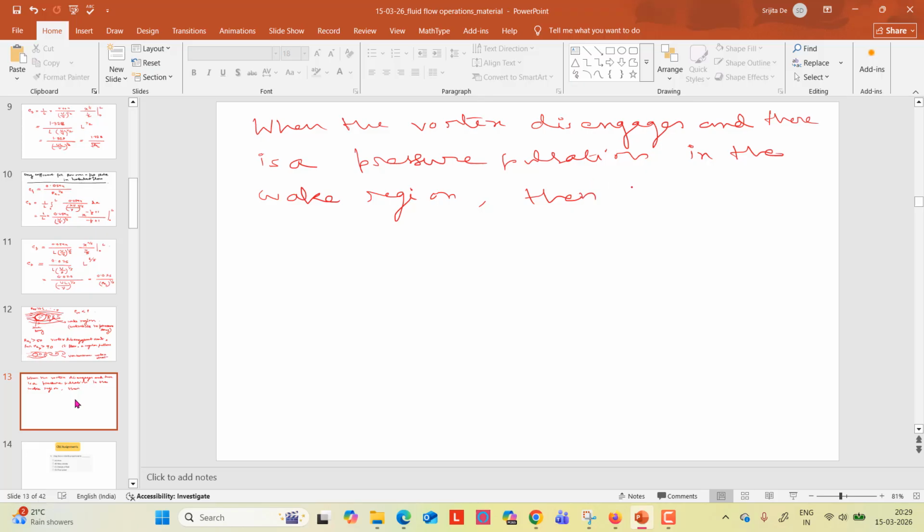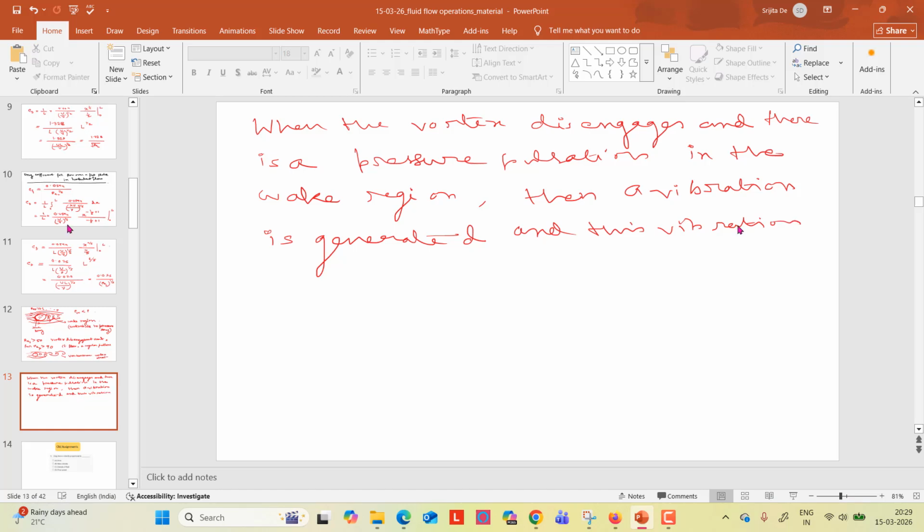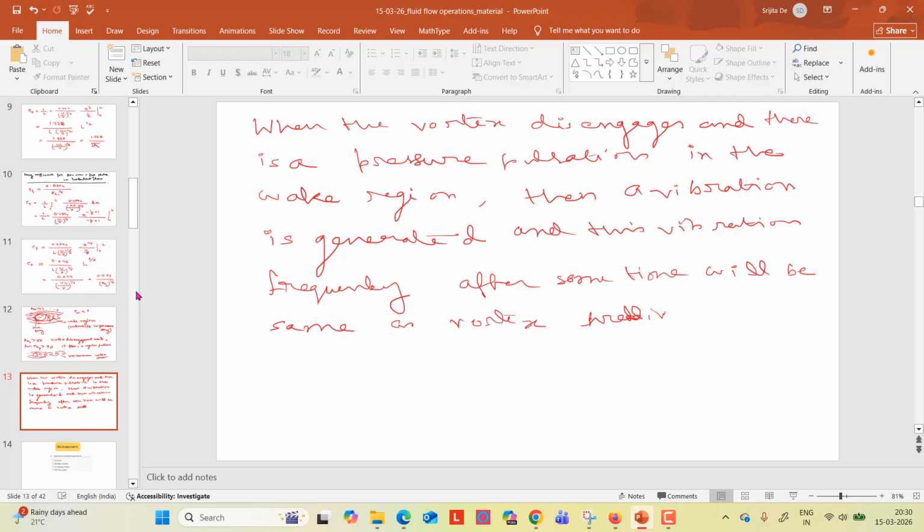Due to this pressure fluctuation or pressure pulsation, a vibration is generated, and after some time this vibration frequency will be the same as the vortex shedding frequency. Okay.